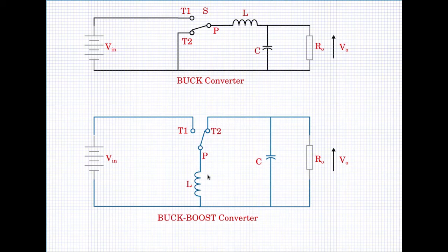So the inductor will charge up this capacitance through the capacitor and the load, and then flow from T2 to P. Which means that the capacitor will be positive on this side as shown here. This will be the positive. So therefore it would be better to connect the capacitor inverted like this, with this side being positive.